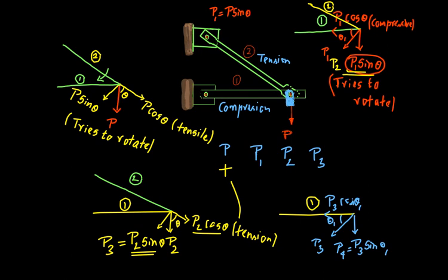All these forces are getting smaller and smaller until you reach 0. You do this a sufficient number of times, and at one point the force is going to become infinitesimally small. It tends to reach 0. At that time, all the forces are completely resolved. There will be no more forces to resolve because the force value becomes infinitesimally small. For all practical purposes, we ignore it without incurring any serious error in mathematics. So the net result is that member 1 will be subjected to compression and member 2 will be subjected to tension.